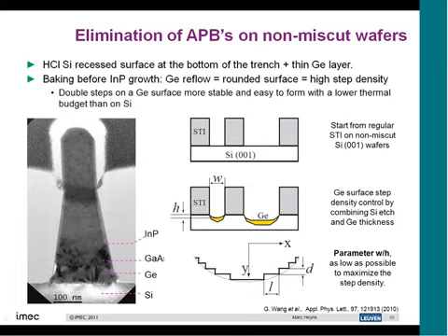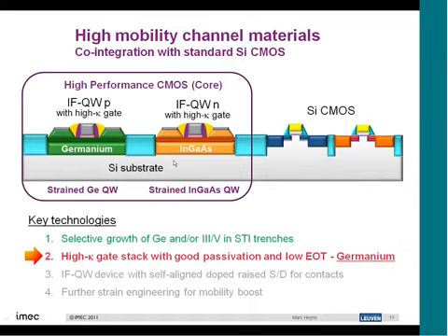And that is actually the ideal surface that we need to again grow the III-V materials without having anti-phase boundaries. So this, for example, is a very nice example of where we have grown such a structure. You see the silicon, you see the germanium that we have put here on the bottom, then the gallium arsenide, indium phosphide, and you see, in this case, a very nice FinFET-like structure here on top. So this means that I think we have a very good outlook on growing these materials onto silicon substrate. That I think is already the first problem that is solved.